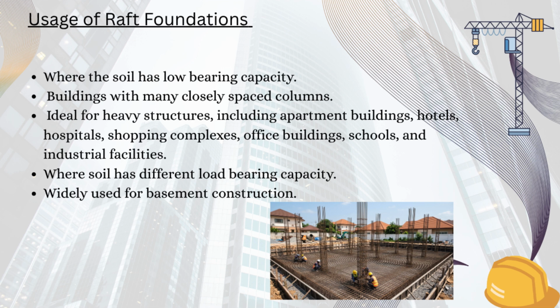Raft foundations are also ideal for heavy structures, including apartment buildings, hotels, hospitals, shopping complexes, office buildings, schools, and industrial facilities. Another major advantage is their ability to reduce differential settlement. Even when soil conditions vary slightly across the site, the raft behaves as one rigid slab, distributing the loads more evenly and minimizing uneven settlement.